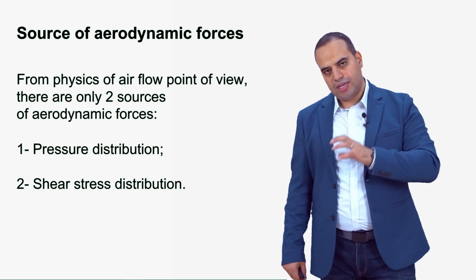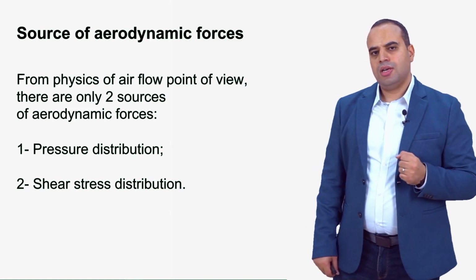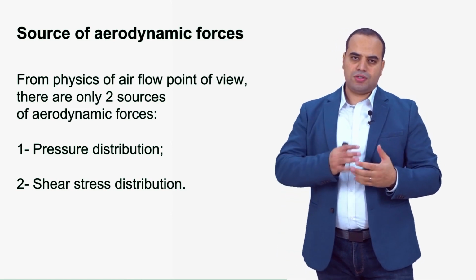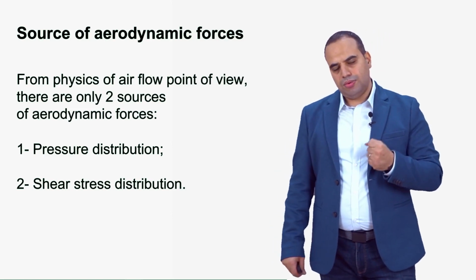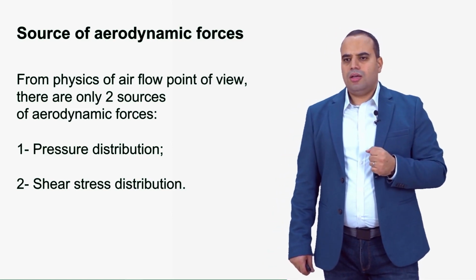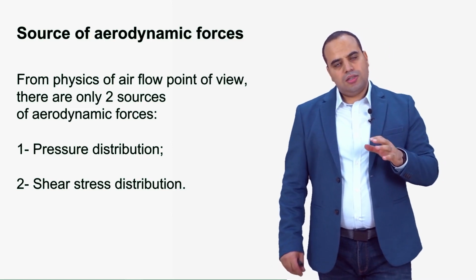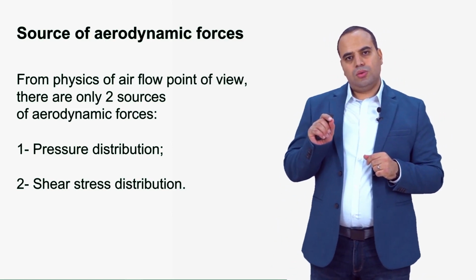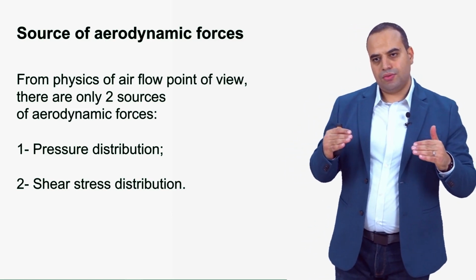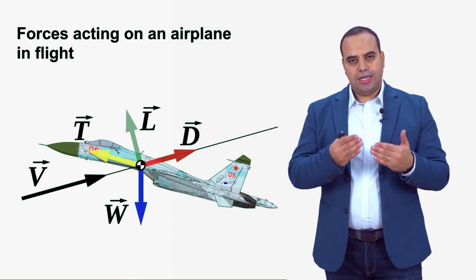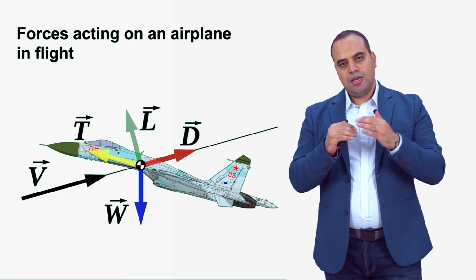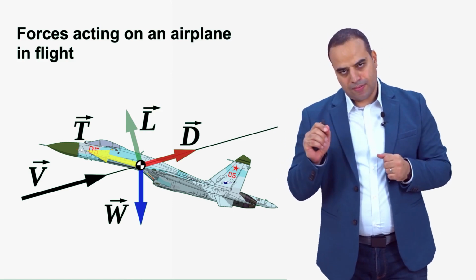Although the viscosity of air is much smaller, probably 100 times smaller than that of liquids like water, right? And water is not a very viscous liquid. It's not a very thick liquid like, for example, honey. Honey is much thicker and much more viscous compared to water, right? But nonetheless, the viscosity term talks about how a certain layer of the fluid is linked to other layers, right? So, for example, if this aircraft is moving through the air, the immediate layer, which is called the boundary layer, on the surface of the aircraft gets a little bit stopped by the friction of the surface, right?